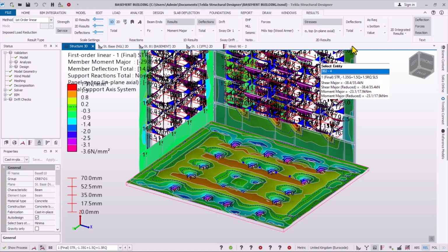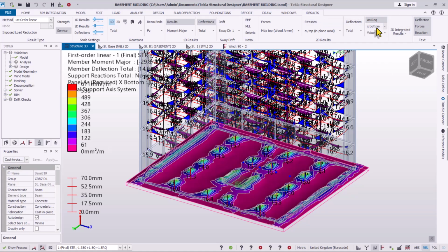So once you are done, you can also look at the reinforcement at the bottom. So this is the area of reinforcement. You can see mm², right? Yeah, these are the areas of reinforcement generated. We have up to 550. This is where much pressure is found. Okay, at 550 area of reinforcement, much pressure is found right there.